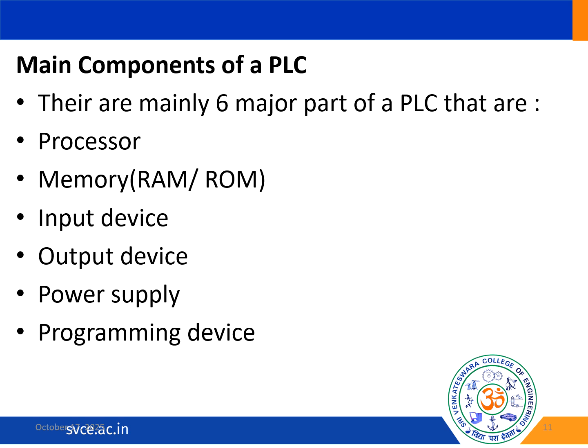When you move on to memory, we can consider RAM and ROM. PLCs have two main types of memory, one is RAM and the other is ROM. RAM is used for storing data and variables temporarily during the execution of the program. ROM is used to store the operating system of a PLC and the user program. The program typically consists of ladder logic. Functional block diagrams can also be used here.